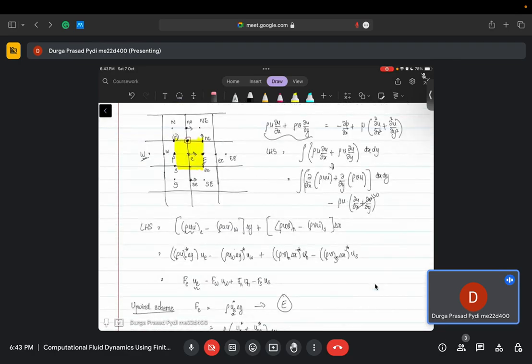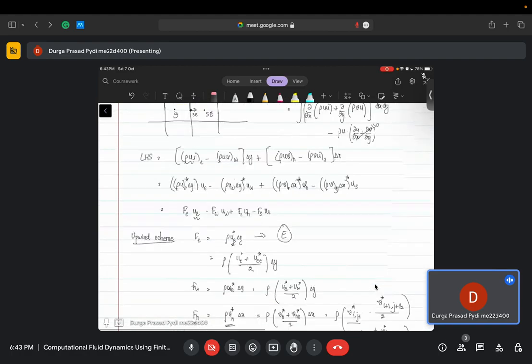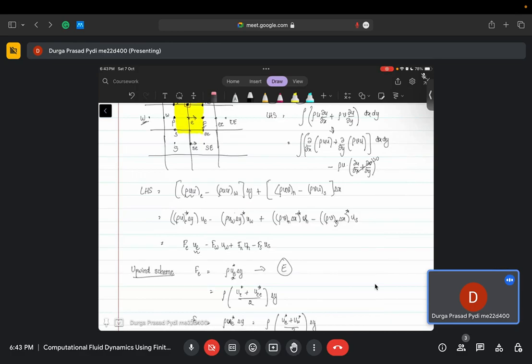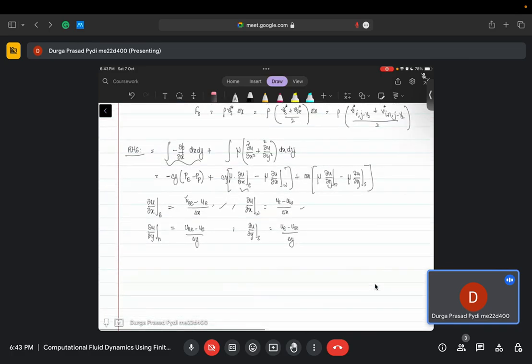So if you are at this particular cell, the red color one, at the north cell face centroid, then you need to take the gamma value as some mean of north and northeast, depending on your del u del y. It's like we have discussed previously, you will be taking harmonic mean instead of arithmetic mean, and then use that as the value of gamma at the face.